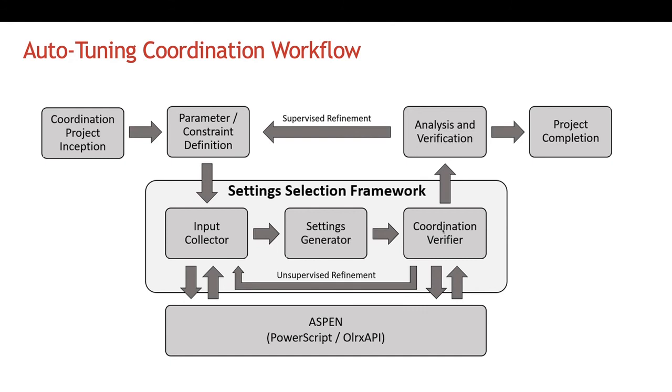And eventually, once it has something that it thinks is a good solution, it's going to propose this back to the engineer and say, this is what I found. You know, maybe it will come back and say, hey, I've proven that within the constraints you give me, there isn't proper coordination. Perhaps this is how I think you should relax it, or please tell me how I can relax this so that I can get a viable solution. And then once that's done, we perhaps go through this loop several times. We complete the project with coordinated settings.